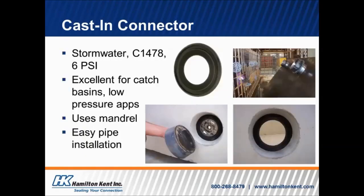Okay, and then here's another type of casting connector. This one is again a stormwater type connector, one that can be used for catch basins or for other types of structures that you just need a 6 psi type of watertight connection. Again, it uses a mandrel. You can see in the bottom left-hand picture that there's a mandrel that they use for that, and then to the right is the final product. So it's really fairly simple to install at the plant, and then it's very easy for the pipe installation as well.